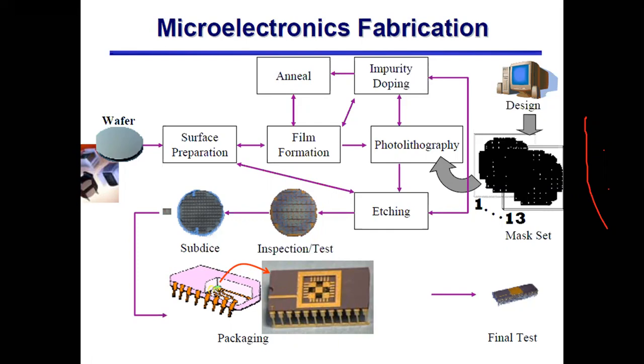Due to this annealing process, the residual stresses which would be produced because of the difference in the coefficient of thermal expansion between two adjacent layers of different materials would be removed. And after that, we have to add a pattern to the substrate.